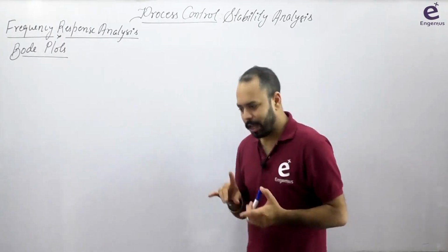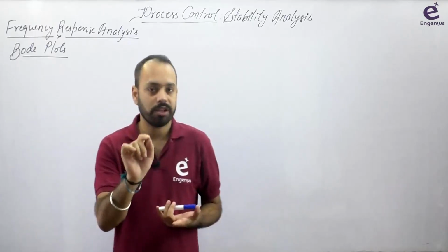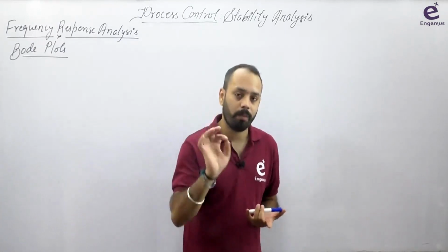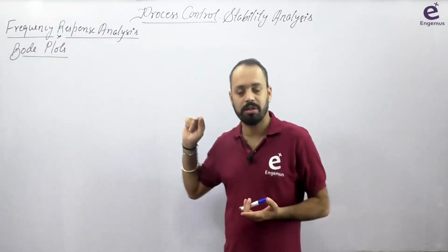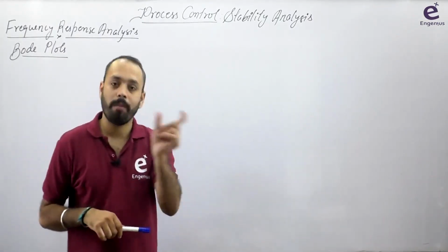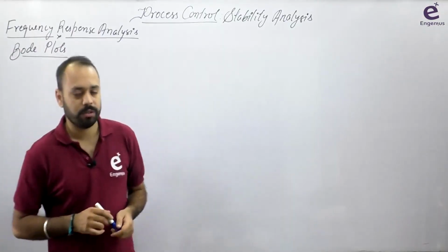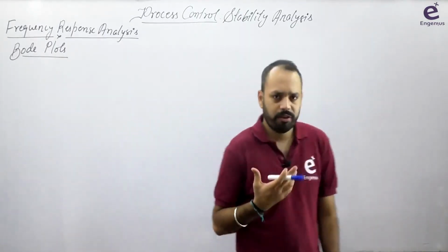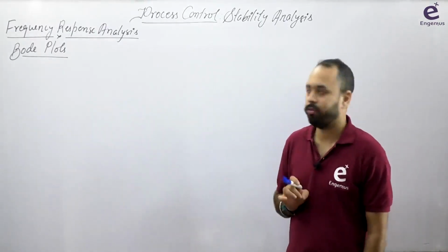Please note that while calculating AR and phi, we only require open loop transfer functions. It is very, very important. However, when we were solving the stability problem by Routh stability criteria, we used the closed loop transfer function. Its denominator, 1 plus open loop transfer function equal to 0, becomes the characteristic equation. So you have to be careful. These are small mistakes that happen many times. The question gives you the open loop or closed loop transfer function. You have to be careful while reading these things.